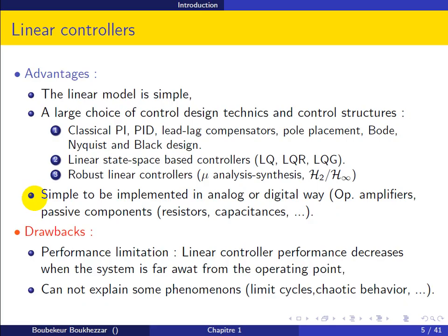We can use both Nyquist and Black charts to design these controllers. We can also use the state space approach, designing linear quadratic or linear quadratic Gaussian controllers using a Kalman filter. A person who has taken a course on linear systems knows these concepts.